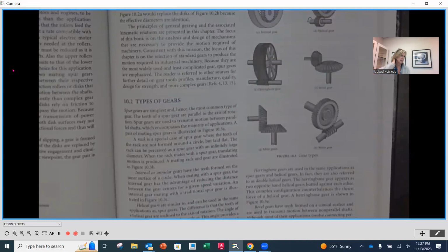So when I was at Hyson, we did high-speed wrapping equipment, and we would run servo motors exactly like this with worm gears on the end of them so that we could start and stop as we indexed, for instance, product into our wrappers.